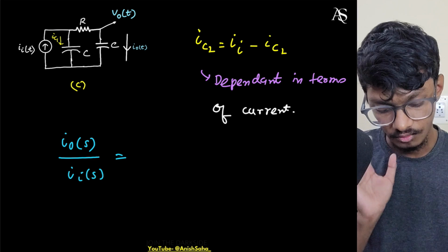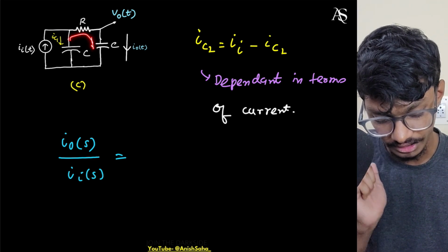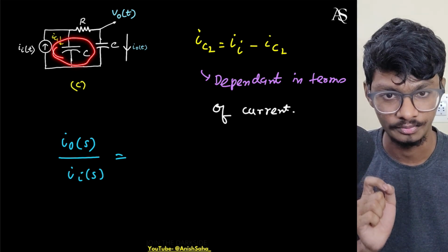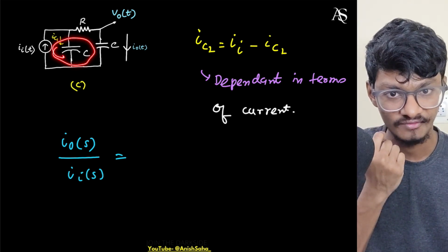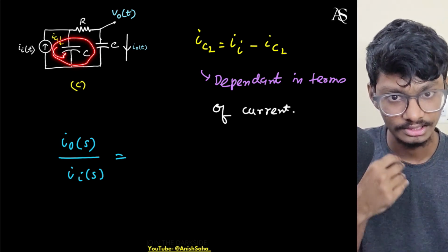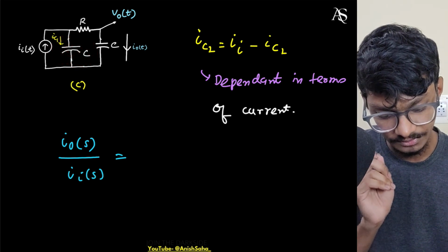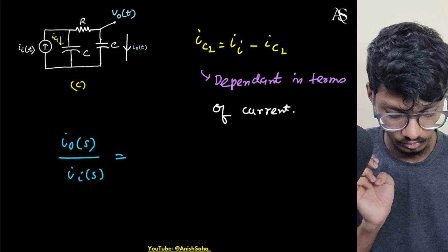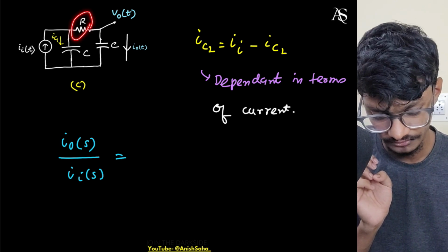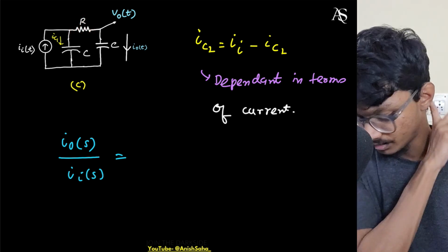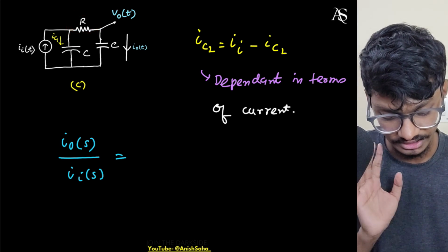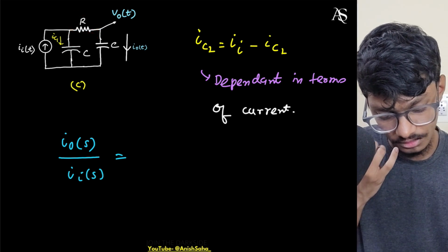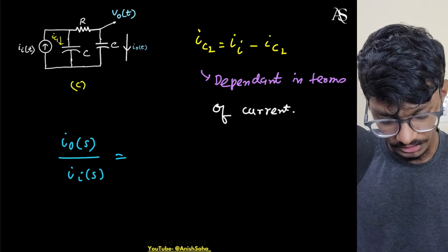So here, where is the 0? My current will be 0 here when this provides 0 impedance. So does this ever provide 0 impedance? No. At s equals to infinity, this provides 0 impedance, which is not a real finite 0. Except that, is there any possibility can I get a 0 over here? No. If this goes to infinity, then only we can get a 0, but this doesn't go to infinity. So there is no 0 in this circuit, right? So there is only a pole.